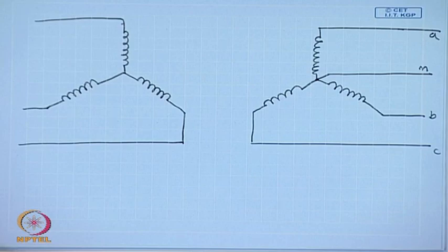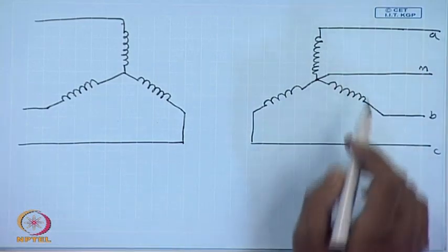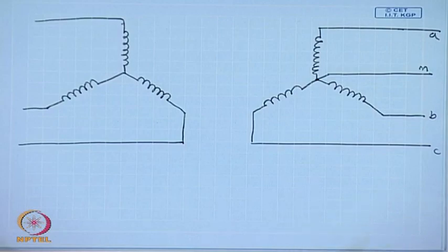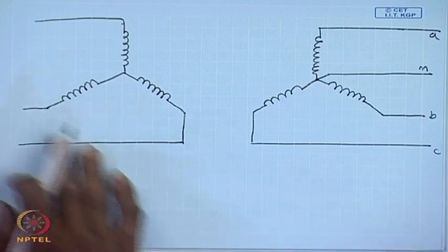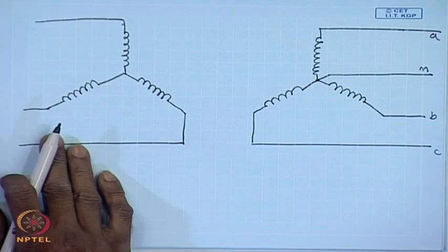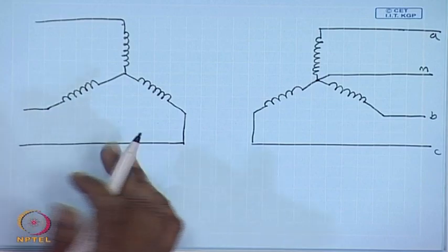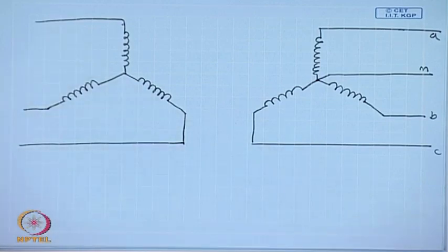that is the zero sequence current of the low voltage side load current and the third harmonic or triplen harmonic currents cannot flow, reflection of that current cannot flow on the high voltage side, which has an isolated neutral. Hence, this produces third harmonic flux distortion. In order to avoid that, some path must be provided for the third harmonic current or reflected third harmonic current, so that the third harmonic flux can be cancelled.